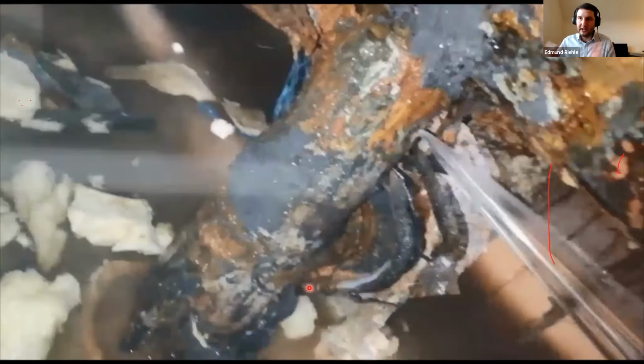And I will tell you exactly when they are on the spot. Not yet on the spot. So with this one, it was a little bit more difficult to tell exactly the position, but now we are on the spot, and now we are further. So in this case, it was a larger pipeline, and the noise was not really very precisely just on the position of the leak, but you could hear it a long distance before and a long distance after.